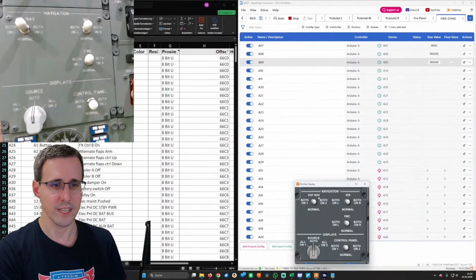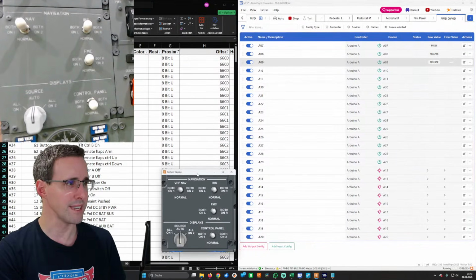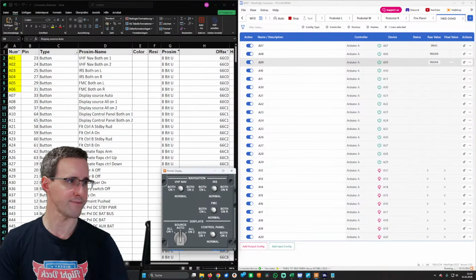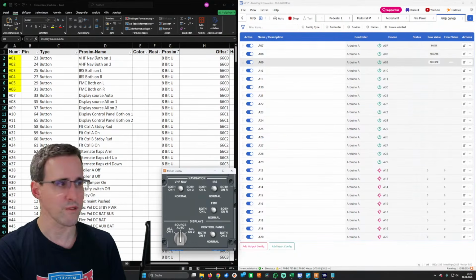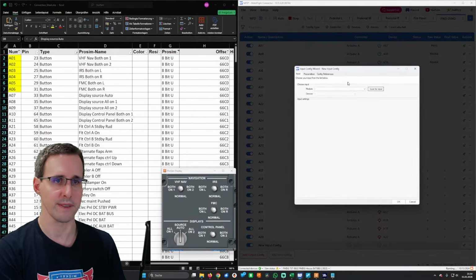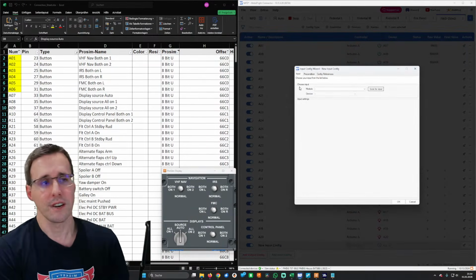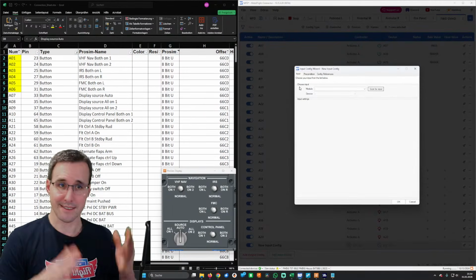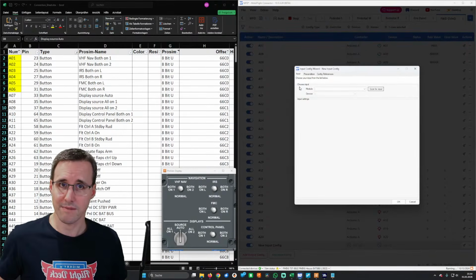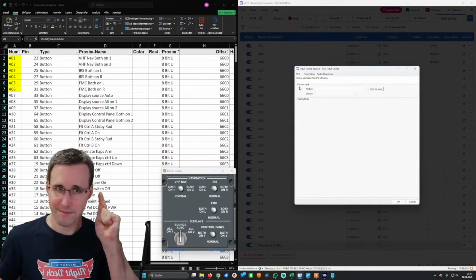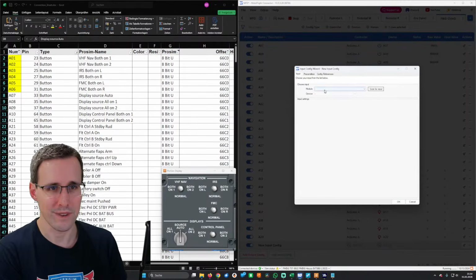Yeah. So VHF nav. Let's make a configuration completely from the beginning. So up here, VHF nav both on, A01. Let's make a configuration. It is an input configuration because we have a switch here. So now, ladies and gentlemen, everyone who hasn't seen making a MobiFlight configuration with Prosim until now, now it's your time, because we are making this really step by step.